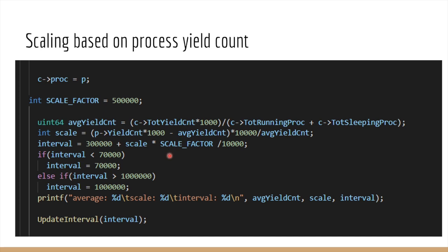One of the difficulties that we encountered when we implemented this was that we couldn't use floating point division. If we use it, the CPU panics, and using integer division is ineffective since it may result in undesirable approximation to a whole number. Especially we had an issue when we calculate the scale, because in most situations the scale could be between 0 and 1 or 1 and 2, and during this time the integer division could approximate to 0 and 1, but we don't want that result.